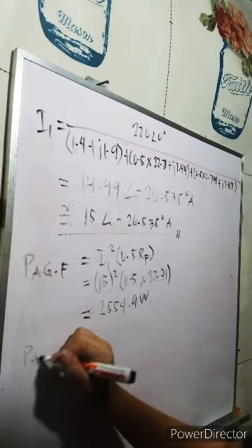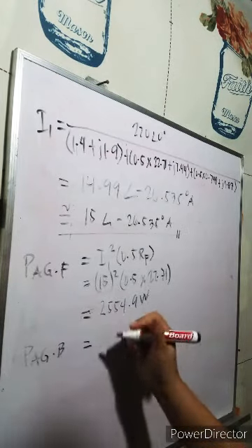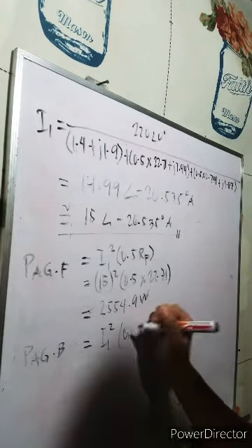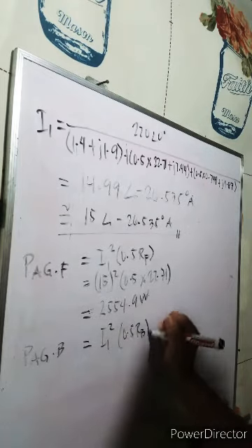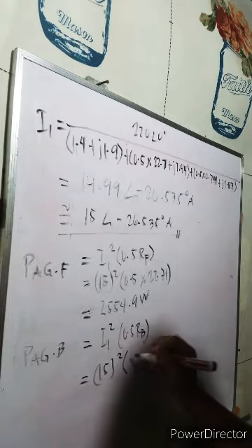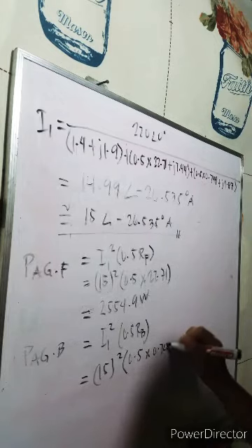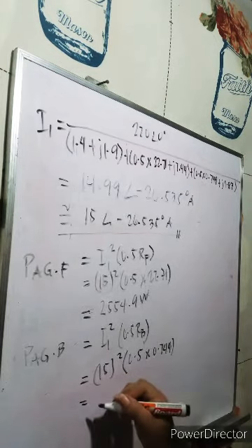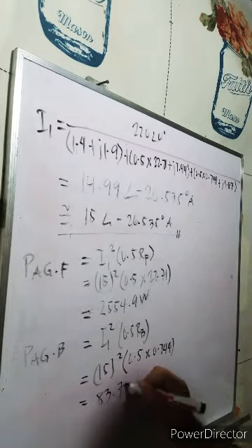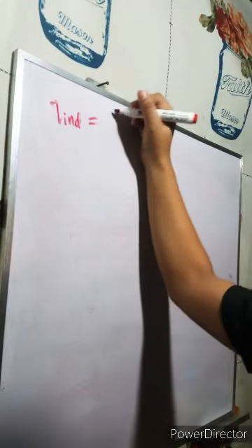So next, the backward air gap power is equal to I1 squared times 0.5 RB, 15 squared times 0.5 times 0.744, so it is equal to 83.7 watts. So since torque induced is equal to air gap power over synchronous speed,